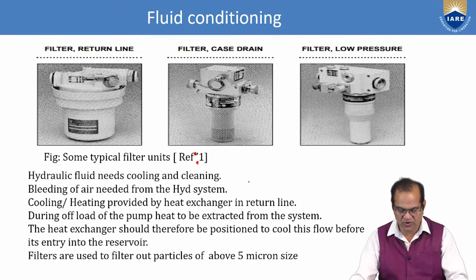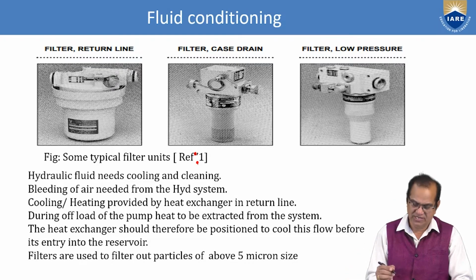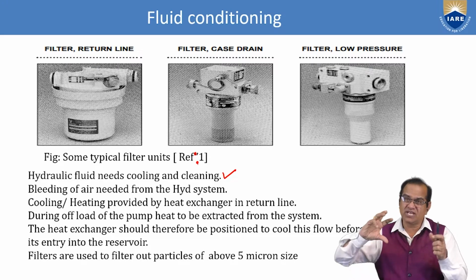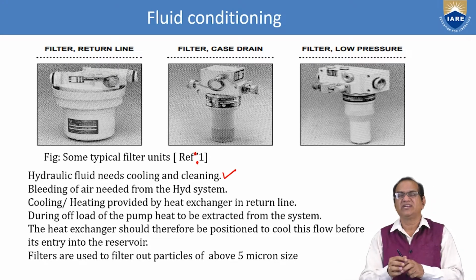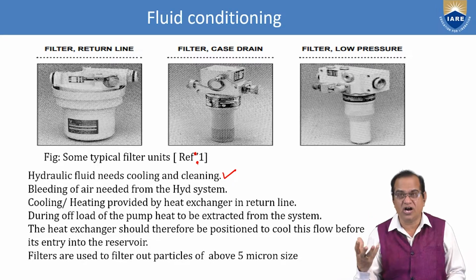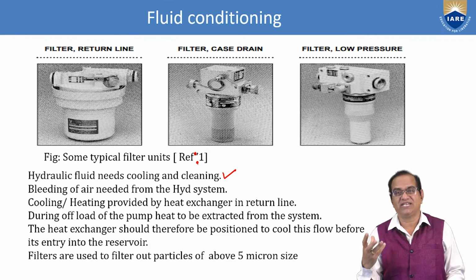Now hydraulic fluid needs cooling and cleaning. So the first thing in conditioning is that we need cooling and cleaning. Your fluid should not be hot, because it is working with the gearbox and a lot of pressure is there. The tendency of the hydraulic fluid is to become hot. But if it becomes hot, it will reduce its quality.